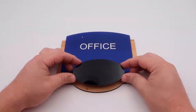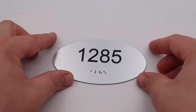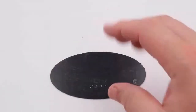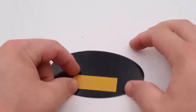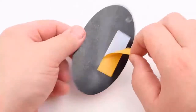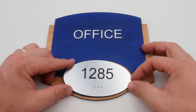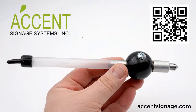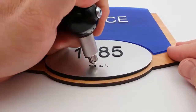So here's our black piece, which is just a spacer or a riser. So I'm going to place that onto the circle there. And now we're going to take our ADA piece, which is the raised letter sign with the braille. And then I'm going to peel the back off. And again, I'm going to apply just a little piece of double-sided over those braille raster bead holes on the back side, and then peel off that double-sided. Then I'm going to apply that whole piece to the surface of the material, making sure you keep it positioned. And then we're going to take our Accent Signage braille raster pen again, and then we're going to actually plunge in the braille dots, in this case, in the same fashion we did on the other ADA sign.